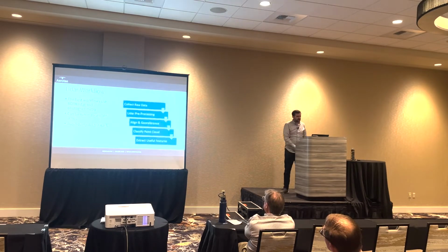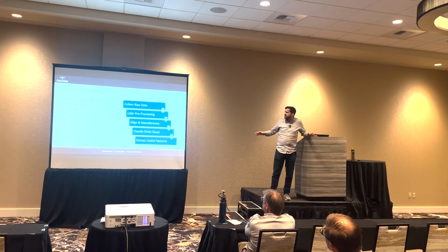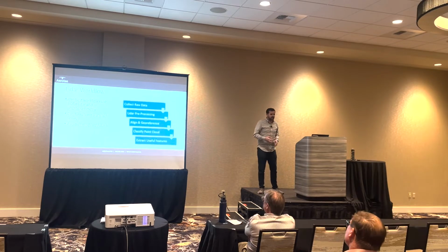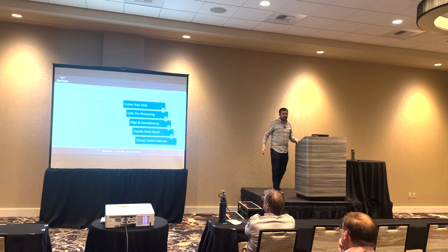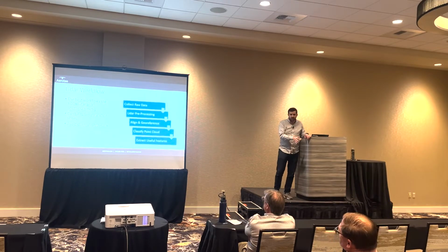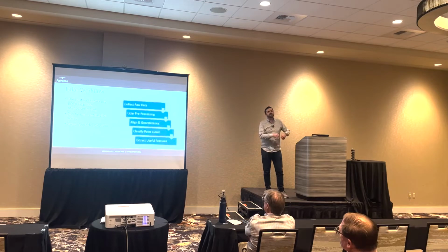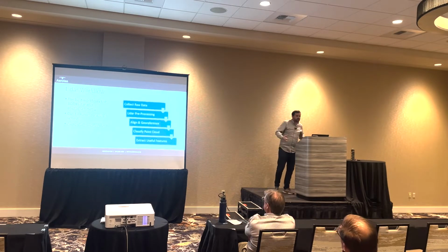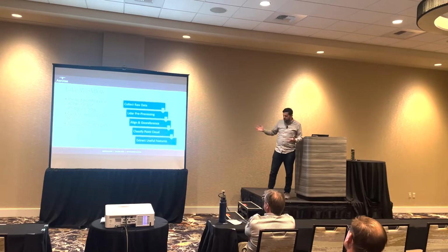And specifically on the LiDAR side of that, this is the workflow that we actually typically use. Now, the best workflows for LiDAR that we found are to use both LiDAR and photogrammetry and blend them together. That can be done, as I talked about a little bit yesterday, in series or in parallel. Series means one after the other, where you typically run your photogrammetry first, and then once you're done with the photogrammetry process, you start working on the LiDAR data. Or, depending on the size of your company or what your specialties are, you might have one person who's a photogrammetry whiz and another who's a LiDAR wizard, and they both work at the same time before combining everything after the fact.